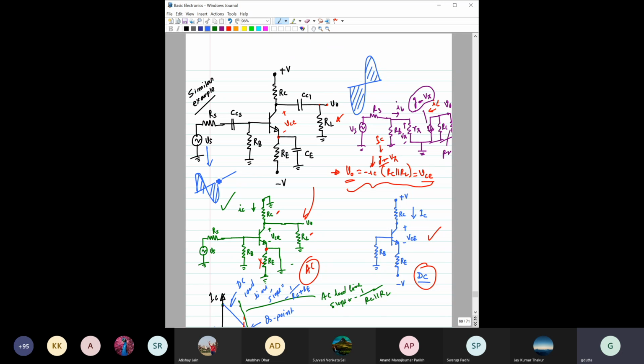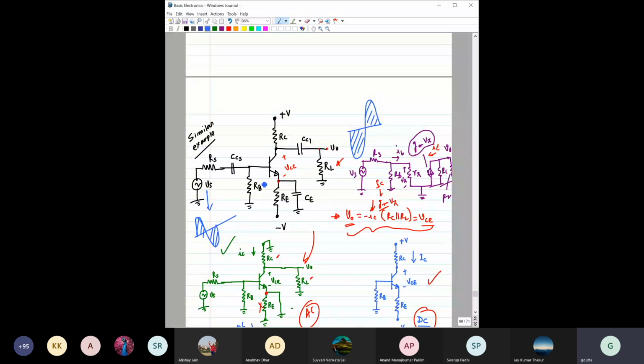Means both sides would be equally amplified, because we are considering this amplifier to be a linear amplifier, right? So the amplification would be same for both positive half as well as for negative half, and it should not be dependent on the amplitude of the signal, right? And this amplifier, this transistor, can act as a linear amplifier only when you are operating the transistor in the active region, right? Forward active region, right? You recall, right?